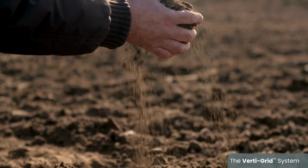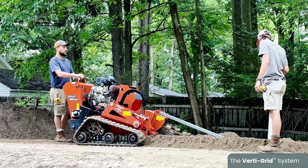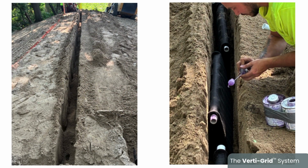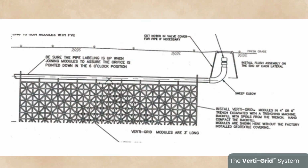Then, trenches are excavated in the top of the mound for the laterals using a walk-behind trenching machine. Immediately after each trench is excavated, the desired number of Verti-Grid modules are assembled end-to-end in the trench. A sweep elbow lateral flushing assembly is installed on the distal end of each lateral for maintenance purposes. These are critical to allow the periodic flushing of laterals by a maintenance provider.